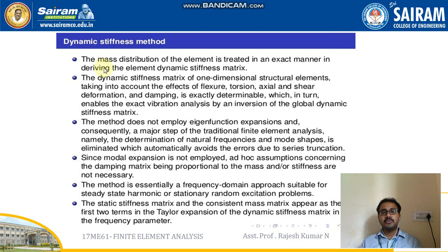The mass distribution of the element is treated in an exact manner in deriving the element dynamic stiffness matrix. The dynamic stiffness matrix of one-dimensional structural elements, taking into account the effects of flexure, torsion, axial and shear deformation, and damping, is exactly determinable, which in turn enables the exact vibration analysis by an inversion of the global dynamic stiffness matrix.